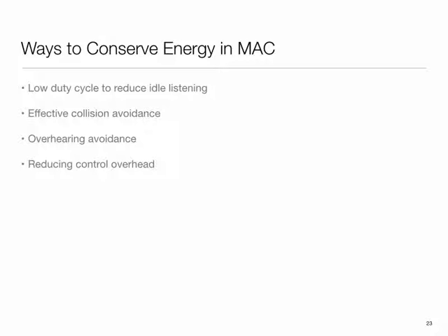Another one is to avoid overhearing. So if two radios are talking, then my radio should not wake up and listen. Somehow we need to avoid this thing that a radio can falsely wake up. And then finally, keeping things simple. If I have to transmit a lot of additional control packets, signaling packets, just to get my protocol to work, again, I'm going to negate all the benefits.